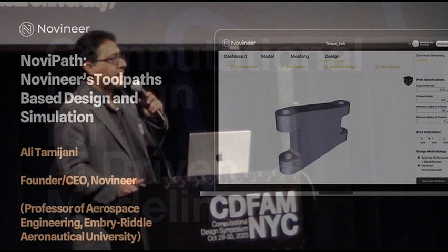If the load and the support are on the same layer, you are very fortunate. That's the best case for layer-by-layer additive manufacturing. Then you can define this unified toolpath, which is going to be much better than changing it in different layers, as you will see. So how much am I going to gain from doing this? 60% improvement in stiffness. Don't change the geometry, just change the path.